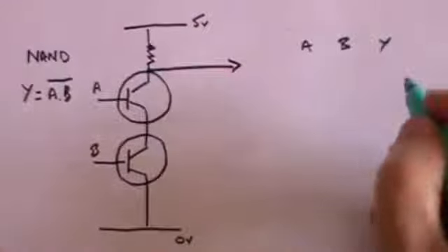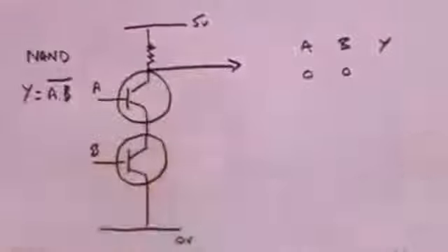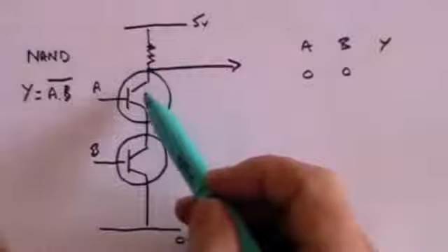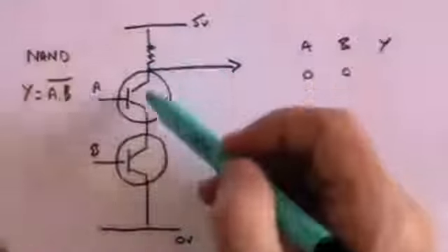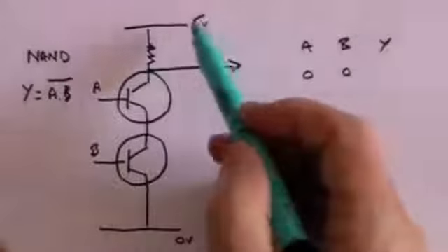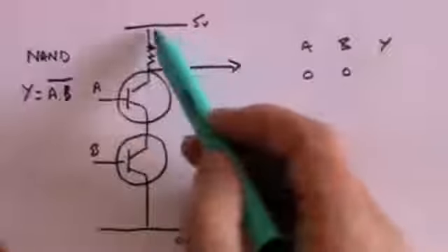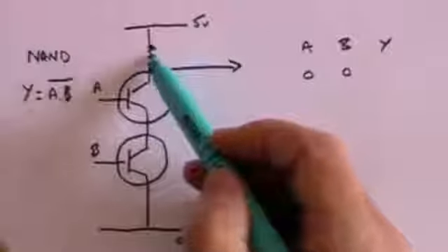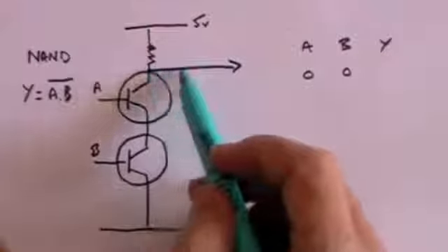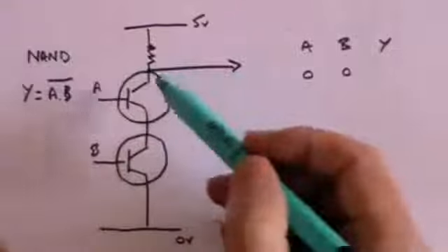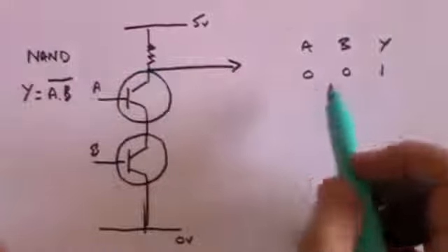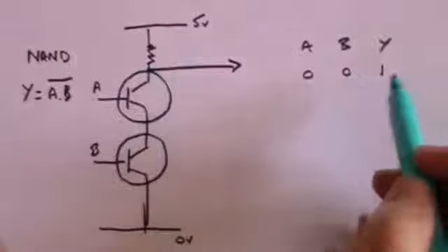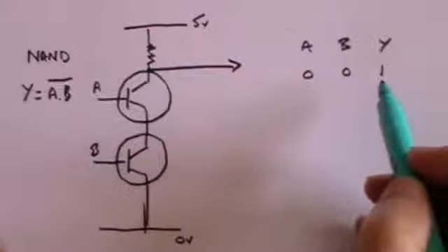So let's suppose that both the inputs are 0 volts. If that is the case, that switch is off, no current can flow through here, and consequently the current will flow this way. Some of the voltage will be dropped across this resistance, but there'll still be a positive voltage here because no current can fall down here, so there's a positive voltage. So if there's no voltage on the inputs, there will be a voltage on the output.